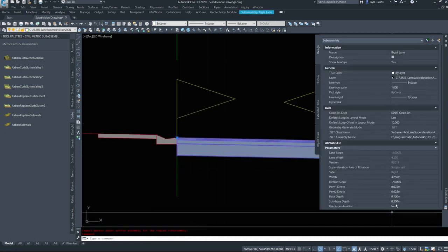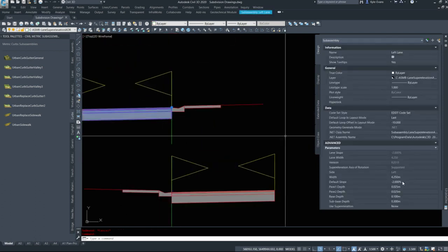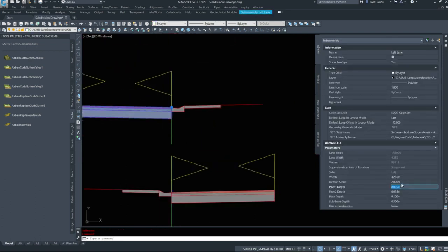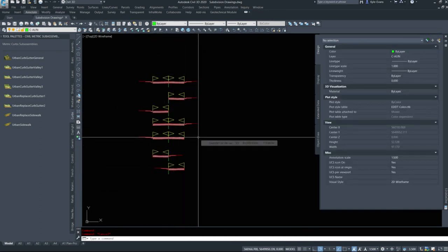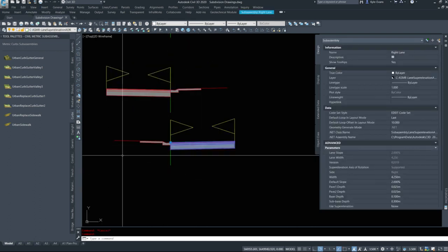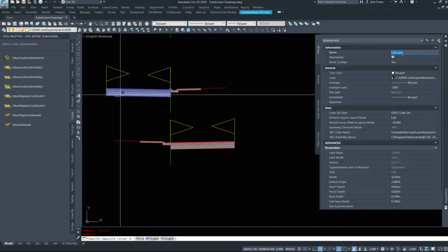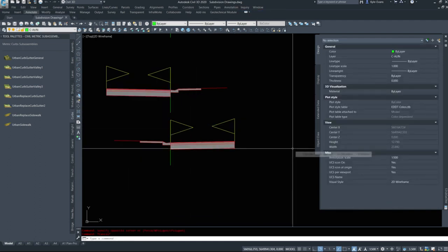So these ones here, we need to slope up at 2%, are basically the ones that will track along any curb and gutters for our knuckles and our cul-de-sacs. The rest of these are mainly for building intersections when we get to the intersection part. Actually, we're not going to name these ones, we're just going to name these lanes. We'll switch the name to lanes because we don't know if it's right or left. It depends on the direction of our alignment.